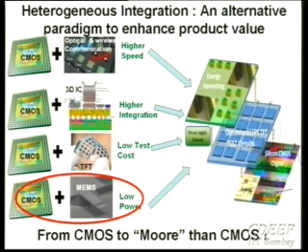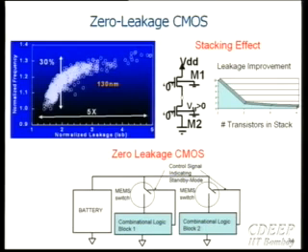The reason your leakage is way better is because the top transistor is going to have a VGS. Because of a little bit of leakage current flow, the VGS is going to be negative, right? So a negative VGS can give you a huge improvement in leakage current, of the order of maybe 8 to 10x. So certainly you can get a large improvement, but the question, of course, is, is it possible? One can very well use it in the standby mode, and people have shown that I can use it in active mode of operation by doing some pre-computations and so on.